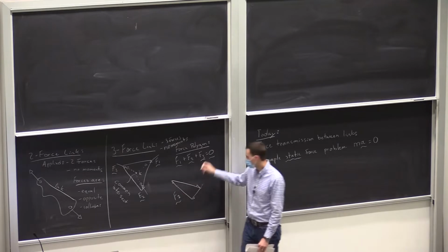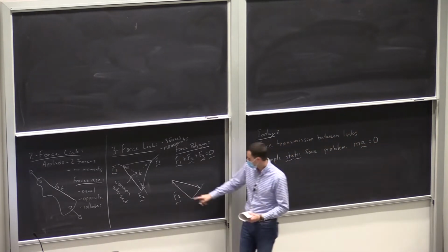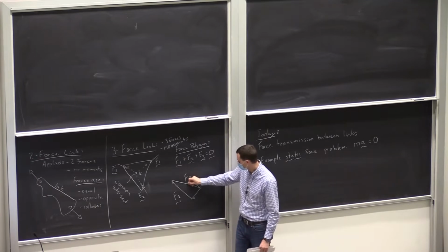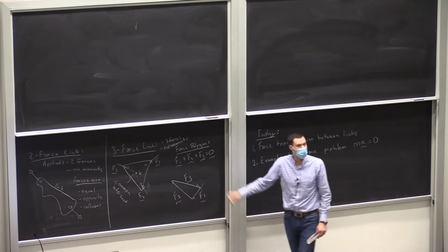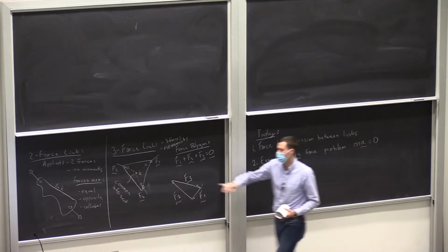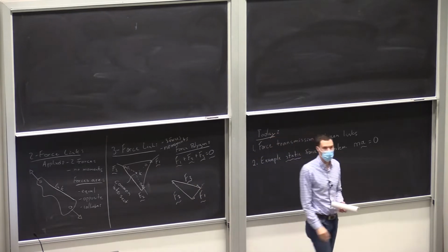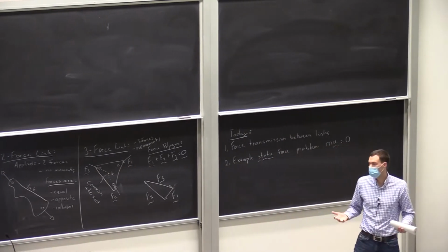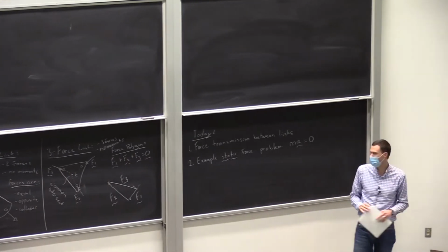And a force polygon for three-force links, they just have three forces. So it's just a triangle. I didn't label these, F3 and F1. So solving for the unknowns comes down to using this intersection point to find some directions, using your force polygon to find the unknown magnitudes. So these are three-force links and two-force links. So we're going to look for those where we can.